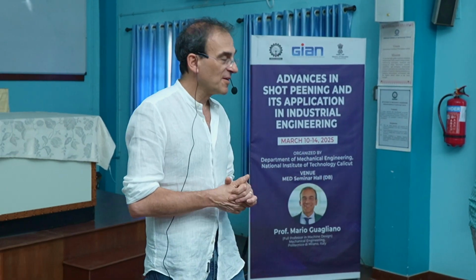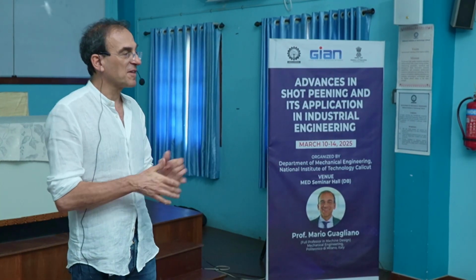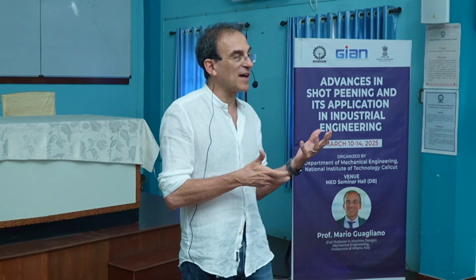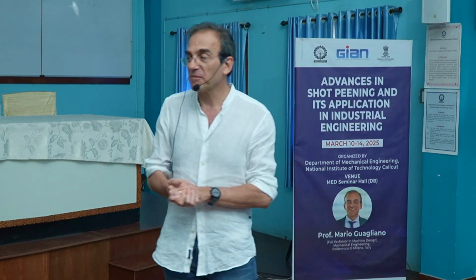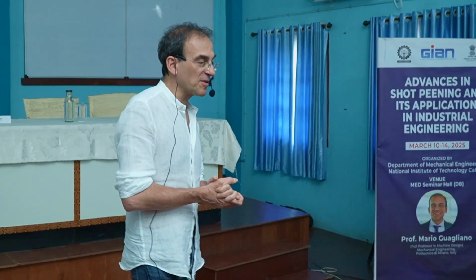Special emphasis will be given to XRD, the X-ray diffraction method, because from a conceptual point of view it deserves a bit more attention, to understand how we can pass from the experimental signal, the diffraction peak, to the value of the residual stresses.